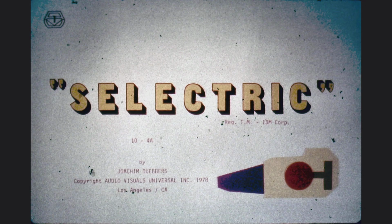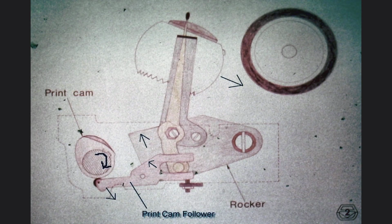Let us start with an overview of the operation of the printing mechanism. All of the printing which the IBM Selectric Typewriter carries out is performed by this one and the same printing mechanism. In this right side view, during continuous printing, the print shaft rotates clockwise at approximately 15 revolutions per second. On the print shaft, we find the print sleeve and a print cam, which provide the power, or the motion, to the print cam follower.